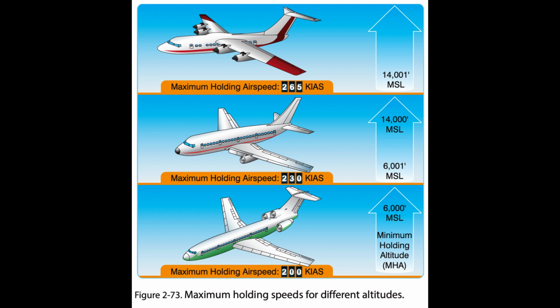For 2-pilot aircraft, the pilot monitoring, PM, keeps the flight plan record. On 3-pilot aircraft, the second officer and PM coordinate recording and keeping the flight plan record. In all cases, the crew member making the recording communicates the information to the pilot flying.